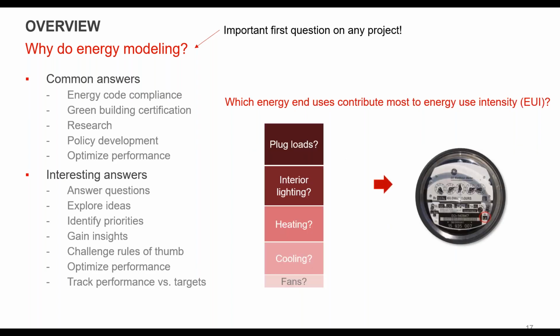You could also be looking at EUI, right? So which end use in your building is contributing to your highest EUI, your energy use intensity. So that might, again, give you an insight of places to look to try to reduce energy consumption.